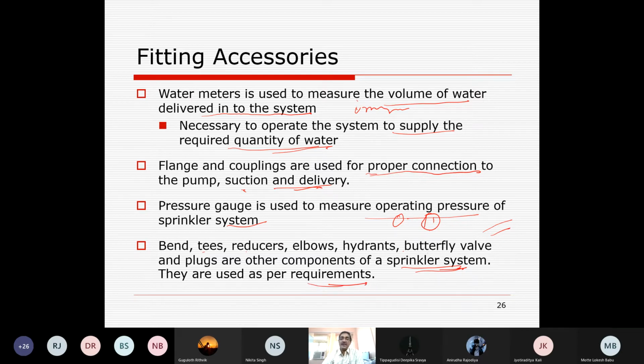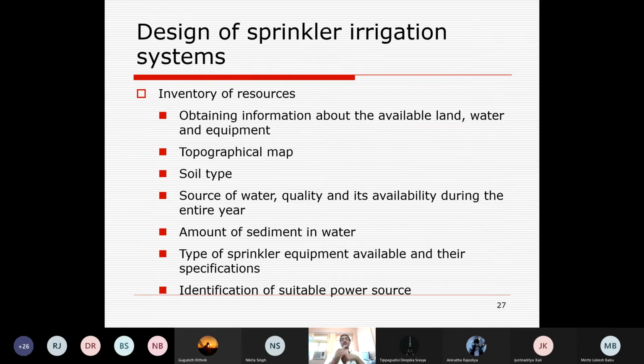And that creates a lot of loss of head of water, head loss, because of pipes, because of fittings. So we need to design the whole system to supply the water with available pump or pressure condition to the crop. So this is design of a sprinkler system. You have another class? Yes, sir. We have another class. Okay, so design of a sprinkler system we will discuss later.